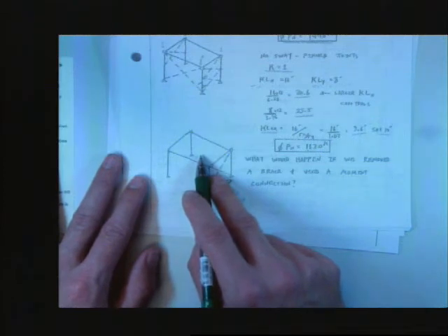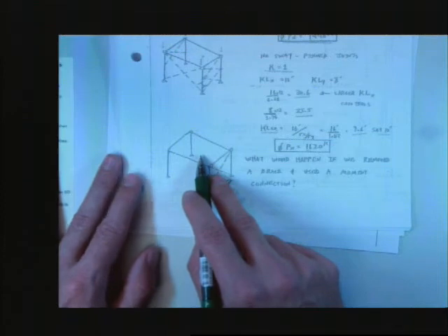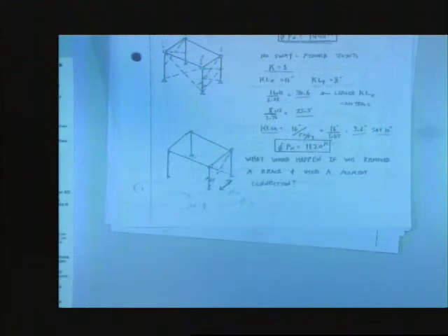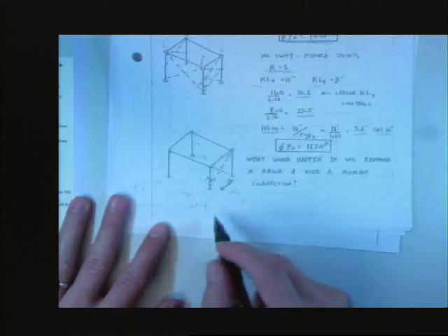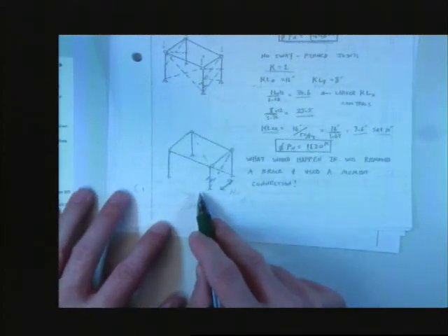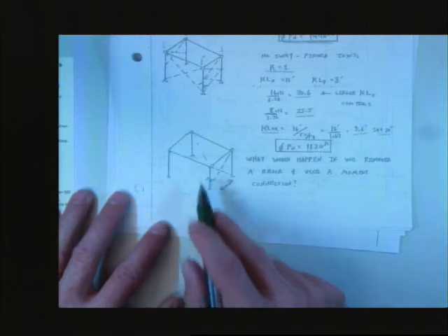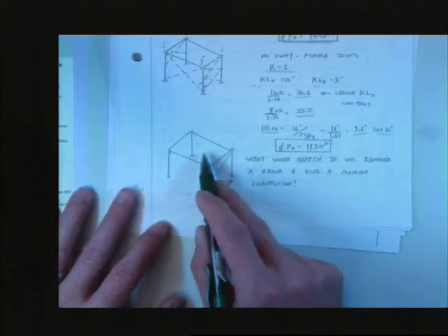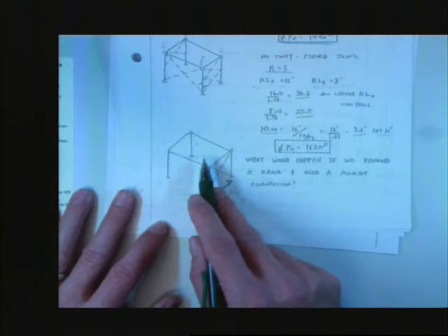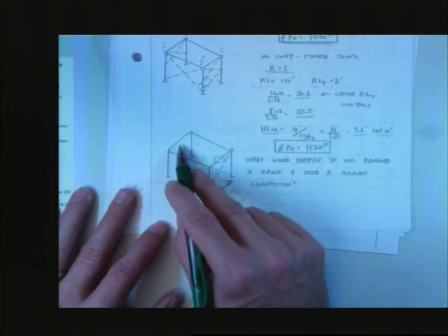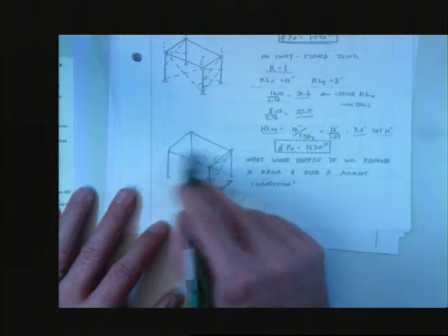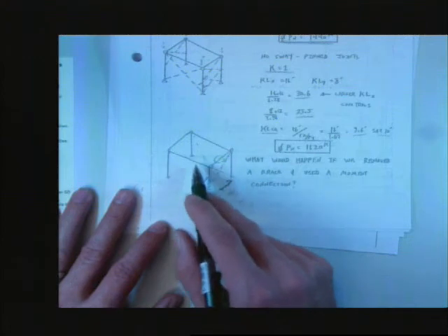Rigid diaphragms are what? Concrete. And also steel roofs with cross braces. It has to have a cross brace in the diaphragm, or concrete. What's a flexible diaphragm? Timber. Flooring system. Steel diaphragm, no cross brace. What's the difference? If it's a rigid diaphragm, we assume that whatever this frame does, this frame is going to do as well. They're linked together by the rigid diaphragm. If it's a flexible diaphragm, every frame for themselves.